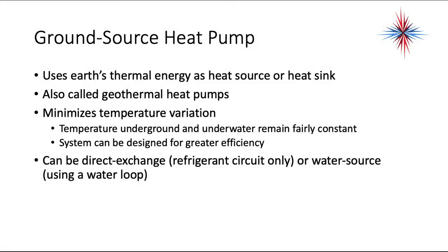We also use ground source heat pumps. It uses the Earth's thermal energy as a heat source or heat sink. It could also be called geothermal. It minimizes temperature variations because the temperature underground and underwater remain fairly constant. This system can be designed for greater efficiency. It can be a direct exchange, in other words, the refrigerant loop is buried, or it could be a water source using a water loop.